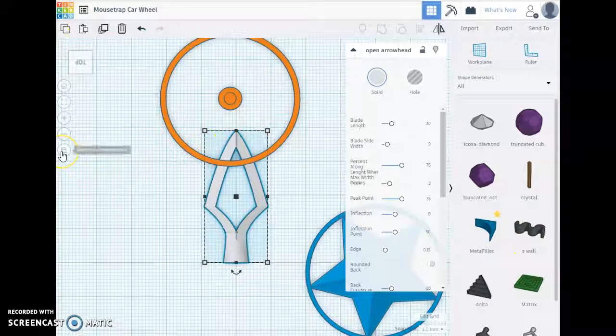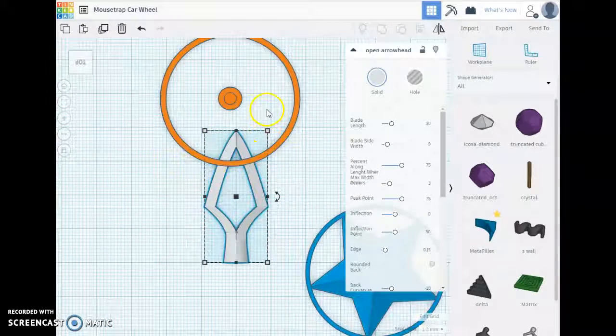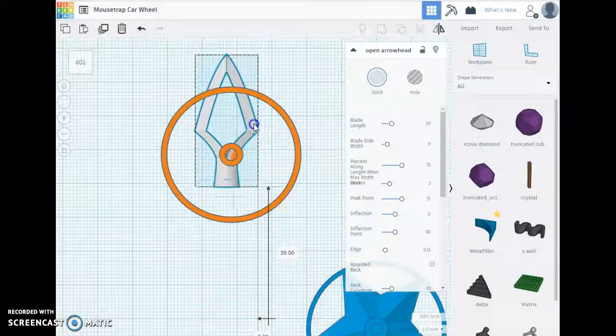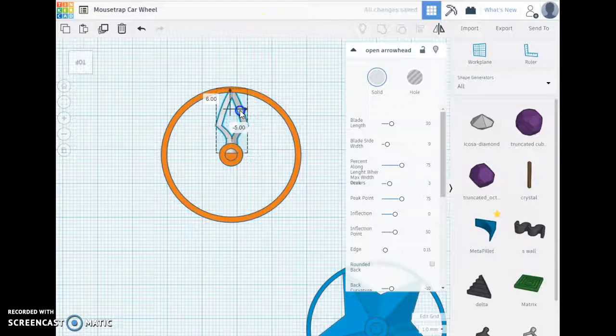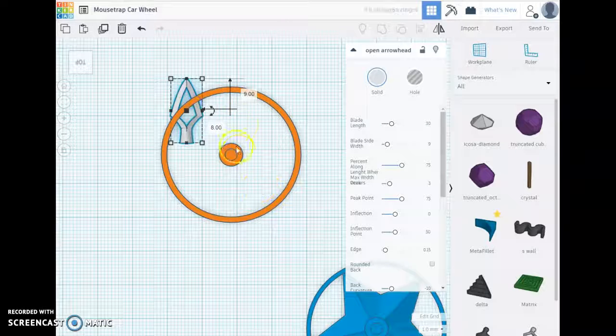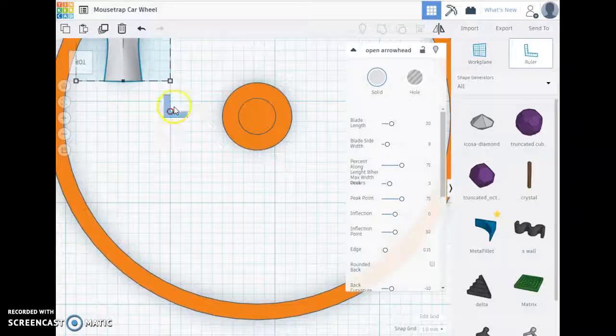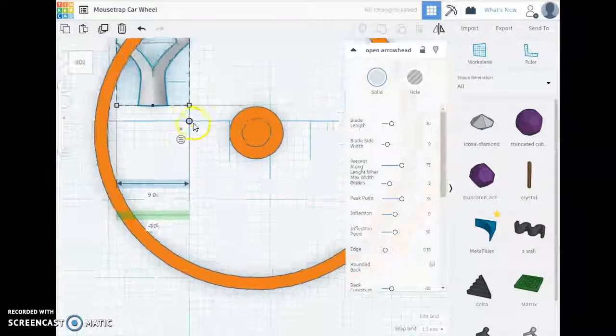Just a reminder, we're looking at a flat view or orthographic projection. That's why this looks flat. We don't want perspective view for doing this kind of alignment. So I could just sort of eyeball what I'm looking for here. Might be really helpful at this point to get this piece centered up with the grid. So I'm going to use my ruler tool, or R for ruler, and place a ruler right there at one of these major intersections where the centimeter grid intersects.